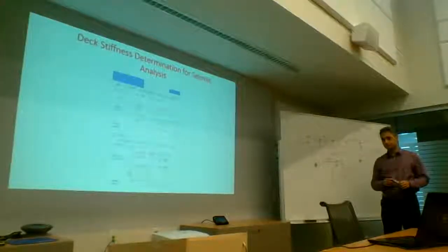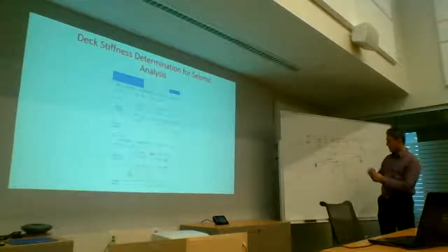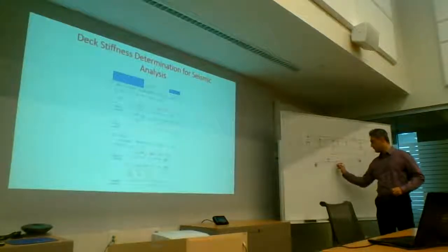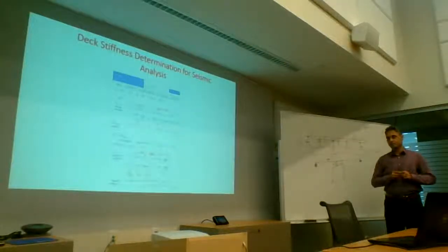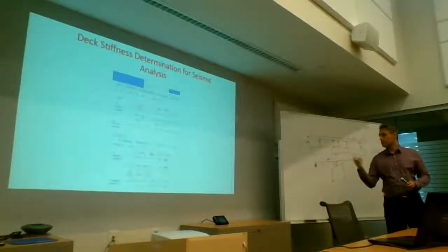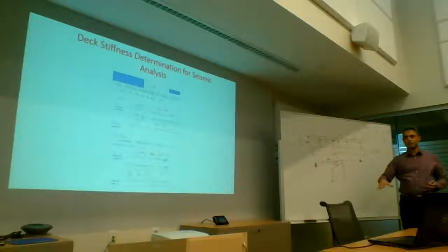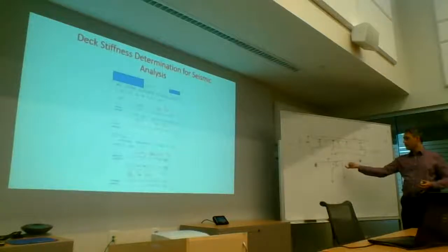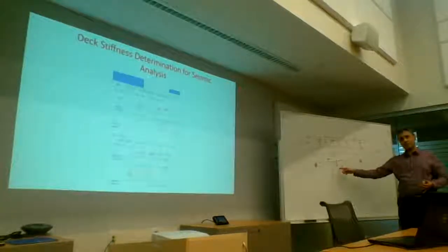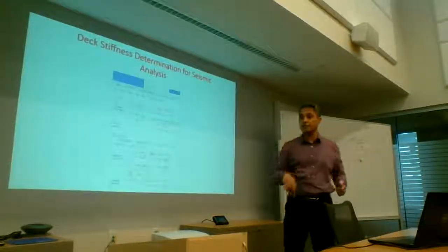So it is also transferring the torque in the cap beam? It's only going to transfer that because of this horizontal load and this eccentricity. The moment, the torque, becomes torsion into your cap. But you will see that torsionally you need to use the cracked stiffness of the cap beam, and it really drops quite low. Once it cracks, you're not even at 25%. In reality, there is very little torsion in these cap beams because they crack very early on. Reinforced concrete cracks very early on, especially in torsion.